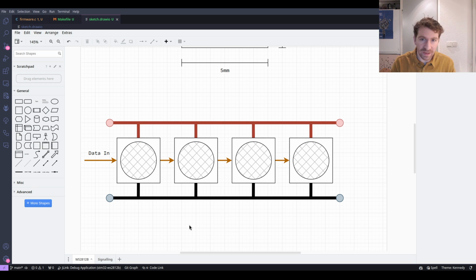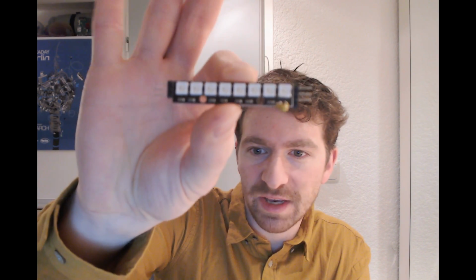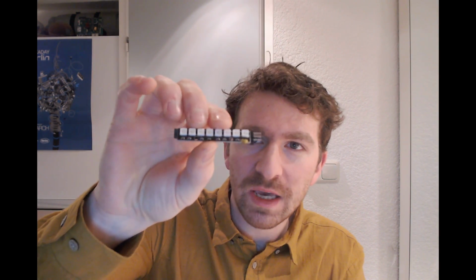I should note that if you get one of these devices, like what I have here on the desk, this is really, I think, an experimentation device, or you can use these to make your own matrices. But if you use this, and especially if you use it with the power supply that's going to a microcontroller, or you're trying to signal things with 3.3 volts, which technically is slightly out of spec for these things, well, you might actually want to add a capacitor to the back.